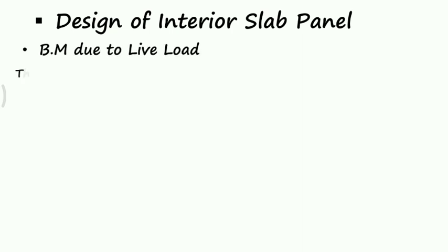Design of interior slab panel. To design, we need the bending moment and shear force: bending moment due to live load as well as due to dead load, and shear force due to live load as well as due to dead load. So we'll start with the bending moment due to live load.